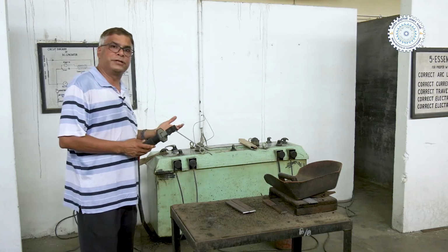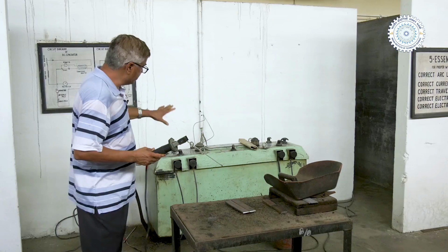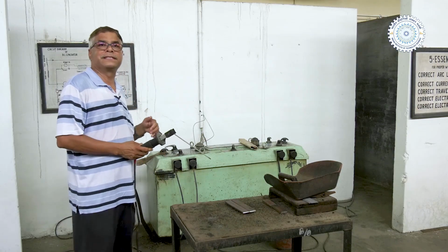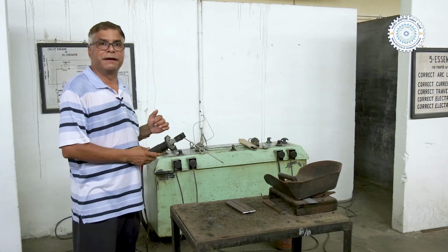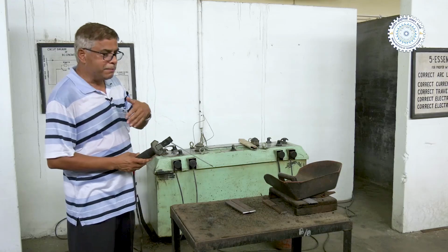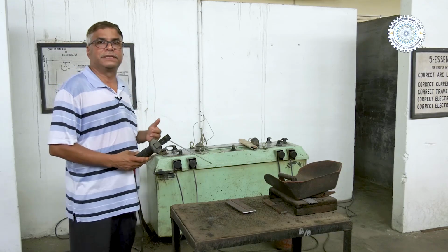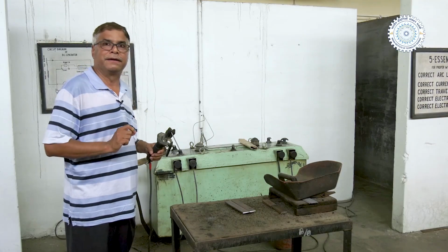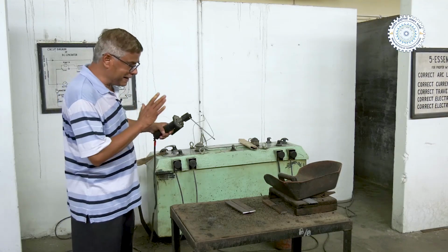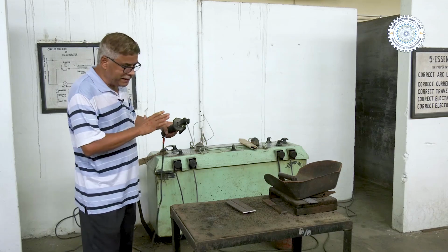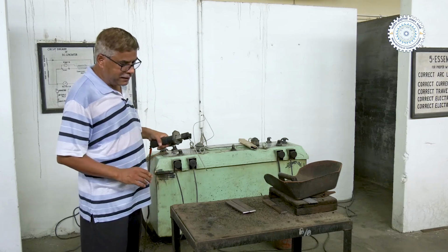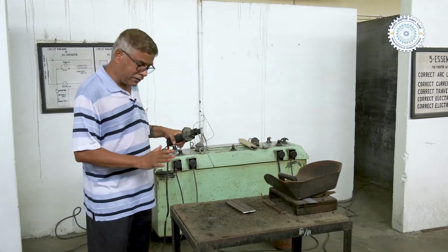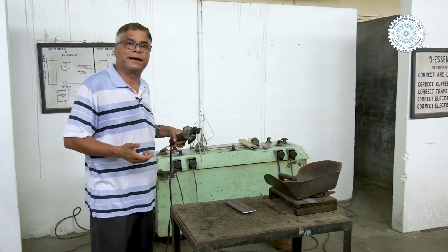Each one will have its own capacity. This particular transformer has got a rating, say, from 25 to 300 ampere. So, depending upon the thickness of the sheet, we set the welding process for the different current values, so that the same will be supplied through the arc to the workpiece